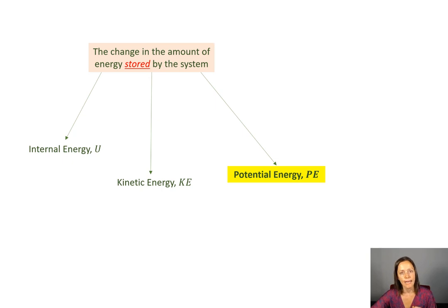All right. Last thing, changes in potential energy. Energy could be stored by a system by internal energy, kinetic energy, and lastly, potential energy. So delta potential energy, changes in potential energy with a capital PE, is in terms of kilojoules or BTU. It's m times g, the gravitational constant, times delta z, which is the change in elevation, so z2 minus z1.